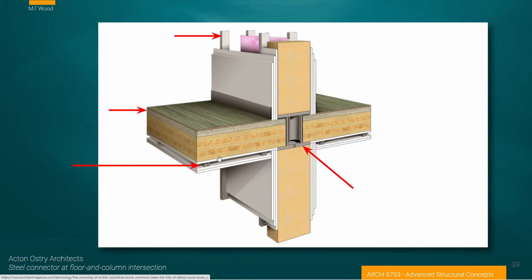We can see now that we have the floor slab, the wood mass timber floor slab, a concrete cap on that, and then it looks like probably finished flooring on top of that. And down here it looks like they've applied a layer of gypsum board, probably for fire resistance. And then they have a channel, which is a noise isolation channel, to suspend 2 other layers of drywall. So there's a lot going on in this construction detail, and a lot of materials are being used.